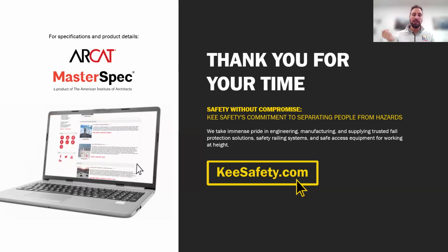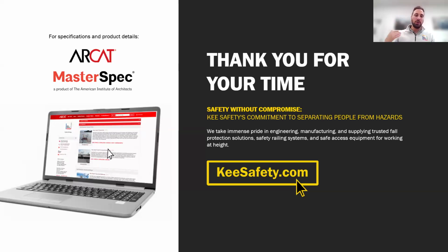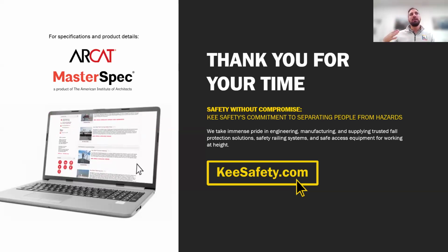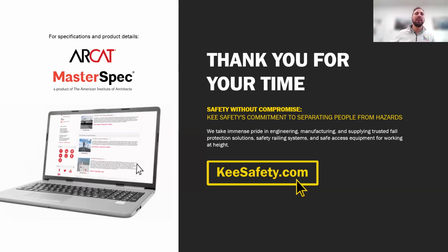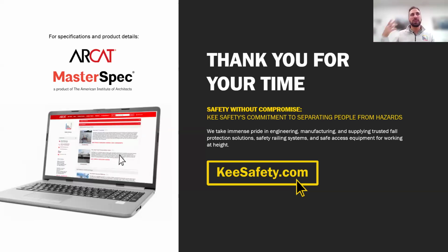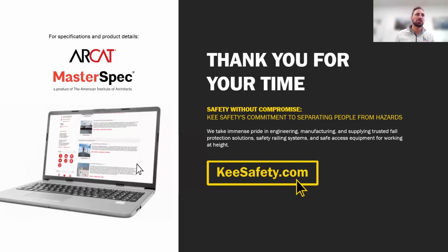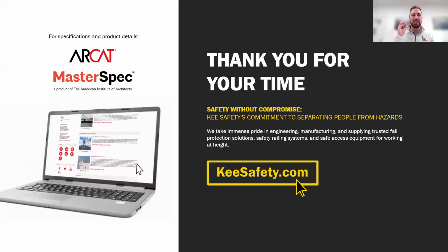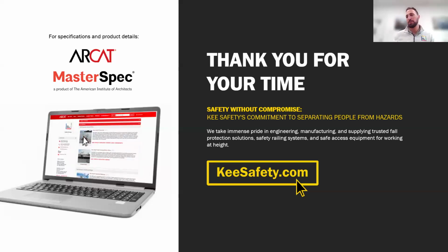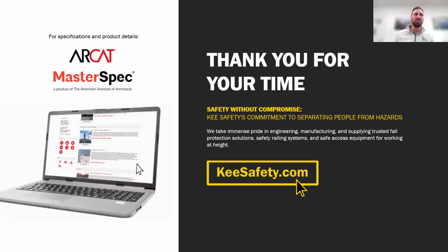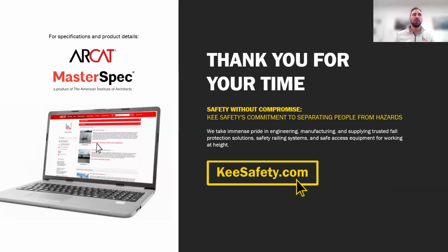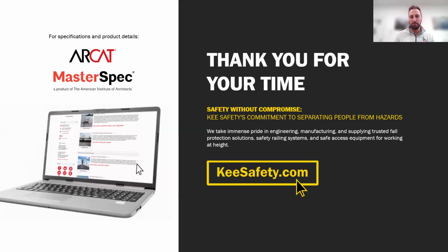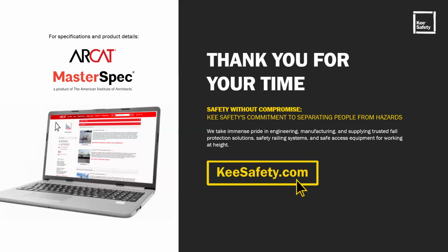But I can officially use a warning line system instead of a guardrail where they just said full perimeter guardrail. And then we would try and get a warning line in as a non-conforming guardrail, which would get written up as a de minimis violation. So they've kind of simplified it. That's a really good question because it shows a very in-depth understanding of the original code and interpretations and what they tried to simplify by coming up with the zone approach with the 0 to 15 foot breakdown.